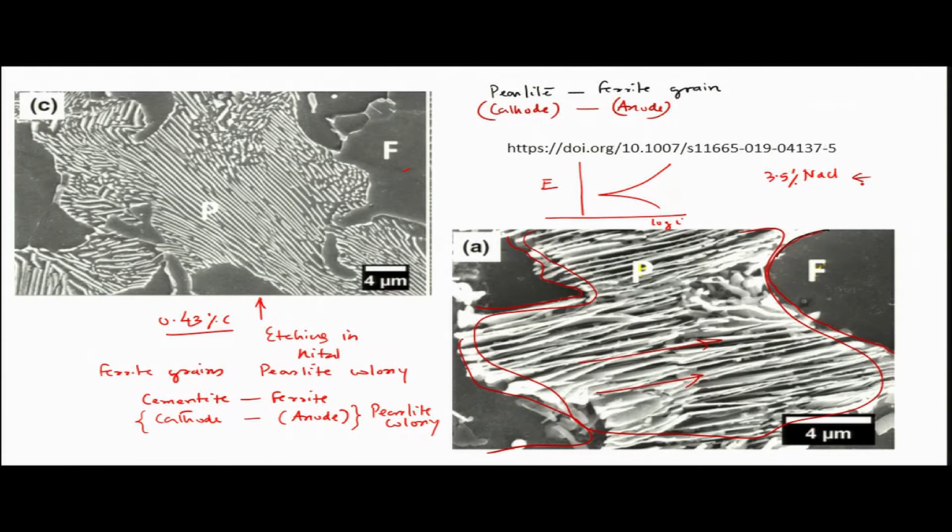Now, question is, when this dissolves, the dissolution effect will be seen adjacent to where the pearlite and ferrite grains are in contact. So, the dissolution pattern will be seen around this zone. In fact, we have seen this particular effect by doing AFM image, where it is very clear if we see the depth profile, here the depth is very high and then it will become like this.